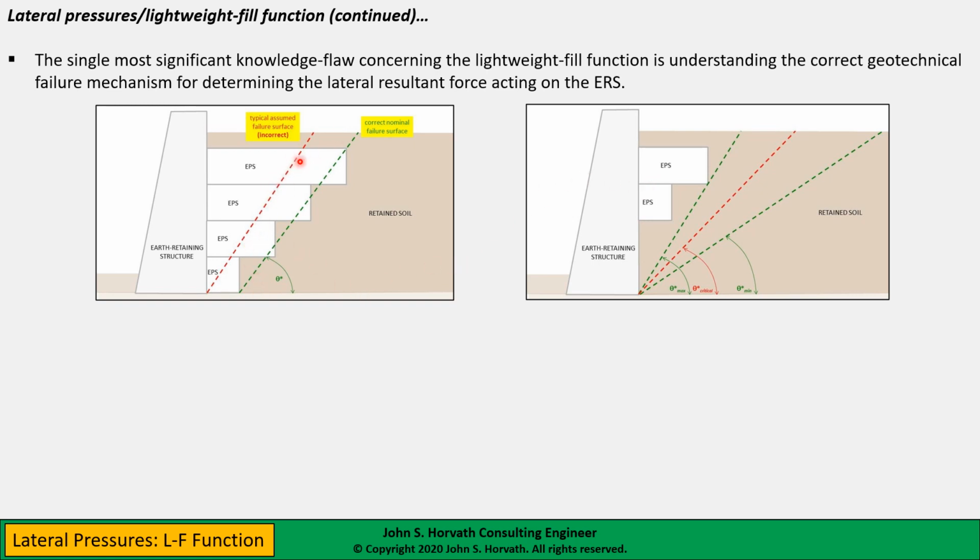Here, the earth force reduction is occurring because you flatten the back of the earth retaining structure, if you will. You have a wall that has a flatter back, and therefore the earth force is going to be less. Here, the earth force reduction occurs because the weight of the failure wedge is less. So these look like the same problem, but the mechanism by which load attenuation on the earth retaining structure is occurring is completely different. This is strictly a weight issue.